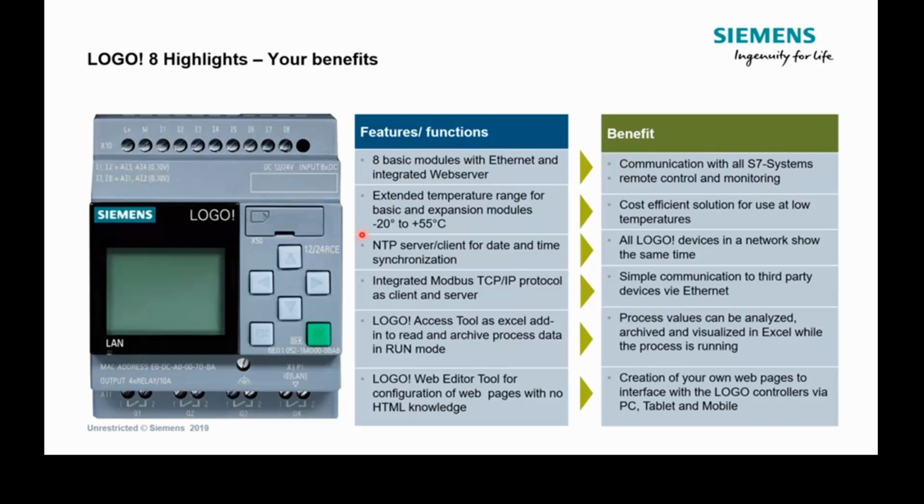We have the extended temperature range through the standard product line from -20 up to +55, as well as NTP client and server capabilities for time synchronization of alarm data, etc. Integrated Modbus TCP/IP protocols as client or server gives us again good flexibility for integrating into a wider third-party network or talking to third-party devices, or even, as we mentioned, up to an S7-1200 as a remote I/O solution there.